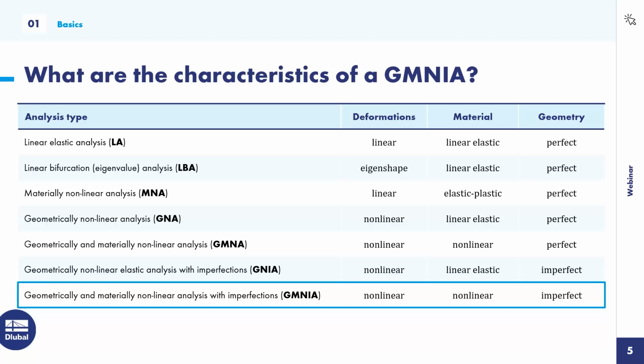To be honest, we could also design a standard plate girder that we tackle in our example today using formulas given in Eurocode 3 part 1.1 and part 1.5. However, if we want to examine special design variants of such a standard girder, e.g. the influence of web openings in critical regions, or we want to investigate how the plate girder performs when we use corrugated webs instead of plain ones, or we have discontinuous sections, in these cases, a GMNEA can often be the most economical design method.